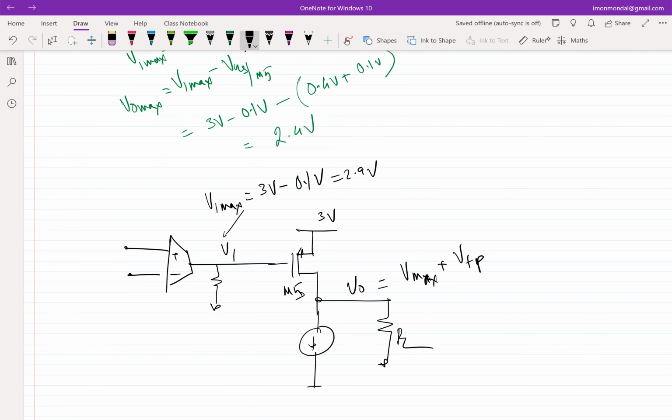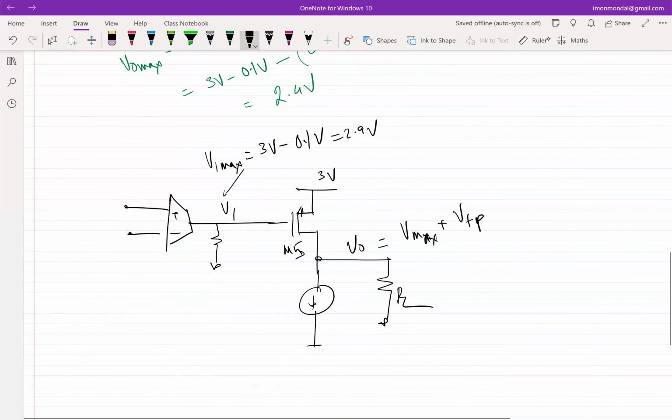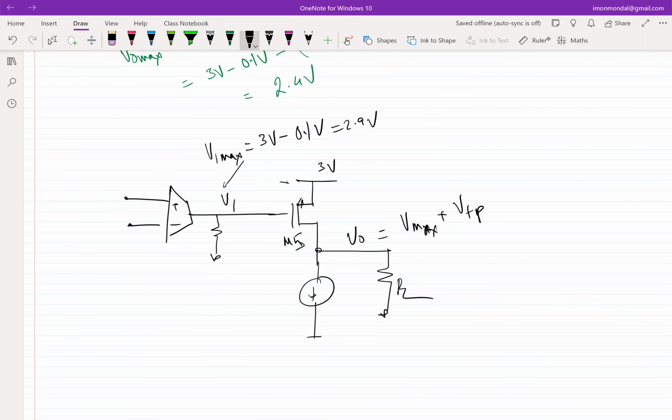Okay. So if you use this PMOS, then you have to give this VGS allowance, right? So this has to be at least some 500 millivolt. But in this case, if you use an NMOS, the VGS allowance goes on the other side, right? But what can V0 go? V0 can go higher than V1, right? Or in other words, if you want to see from the source side, you'll have to keep one overdrive between the source and the drain.